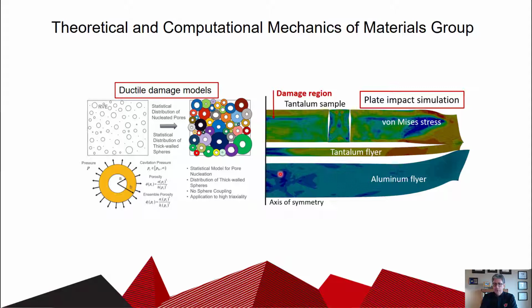So most metallic materials are what are called polycrystalline, and they are aggregate composites of single crystals, and typical sizes of these single crystals are going to be something like 50 to 100 microns in general. And so that structure of single crystals for these metallic materials is a very important contributor to how these metallic materials damage under conditions of very high stress loading, the example of which was that impact problem.